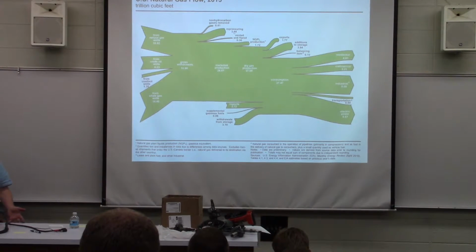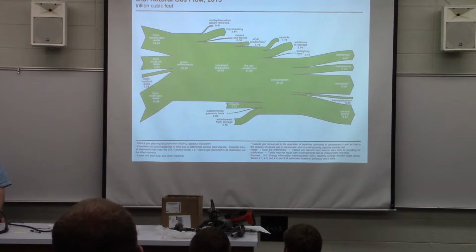There's repressuring. So what do you think, what's that gas doing? Where they label it as repressuring. Going into energy to pressurize the rest of it. Yeah, exactly. So you're both right. It's being used by us as fuel in these compressors to recompress the rest of the gas, right? It's a pretty significant volume that gets used.